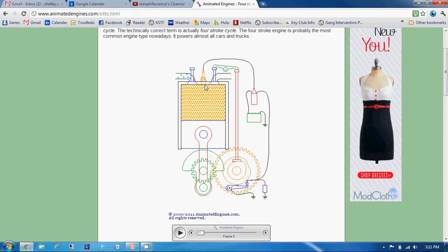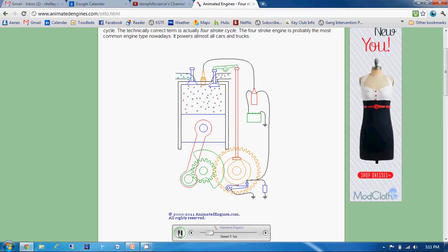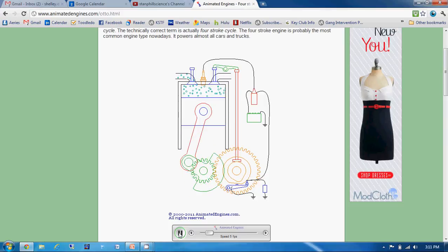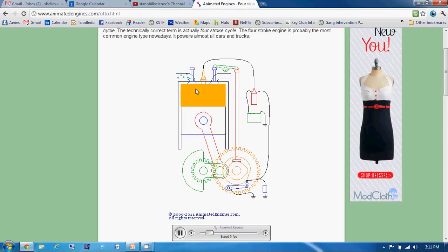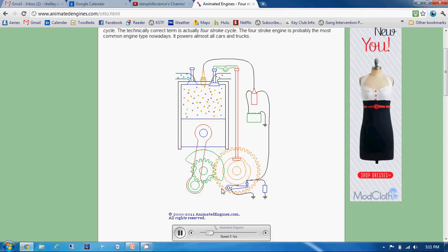This is where we really get the power behind our engine functioning, that rapid expansion of the hot combusted air. And then finally we'll open this valve and push all of that combusted air back out. There we go. Alright, so once again we'll go through it step by step. We have the intake, it gets compressed. Here's where we get all that heat energy that drives this gear around, and that's what enables our car to drive, basically. It's what is then able to be converted into usable work that can power other mechanisms.